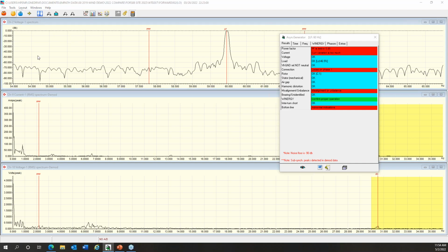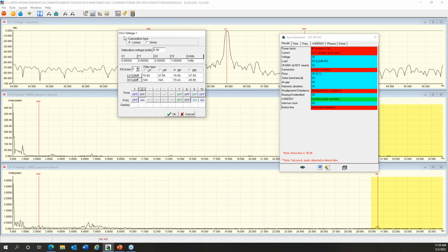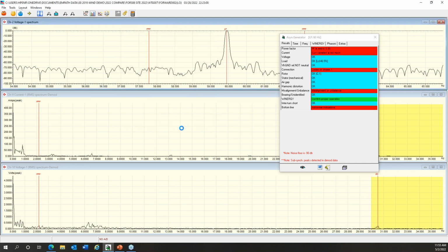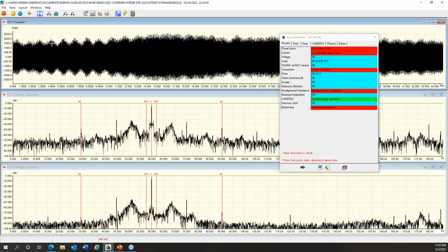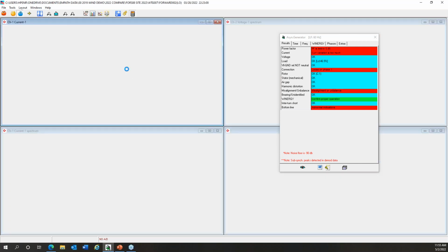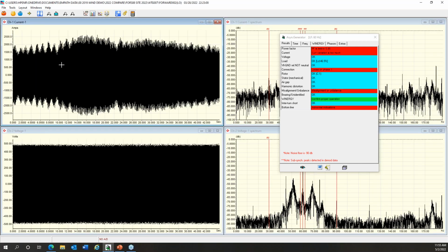So on the high frequency spectra, running a couple of screens here. Let's get rid of some of that stuff. Sometimes I'll do this just to get a look and see what current looks like. And see this little wavy spot here? If I look at voltage and I see that as well, then I might have a little more concern that I might have something else going on. Nope, nice and smooth. So this could be something with the gearbox causing hesitation. This could be an actual load. It could just as likely be something going on with a wiring or brush circuit.